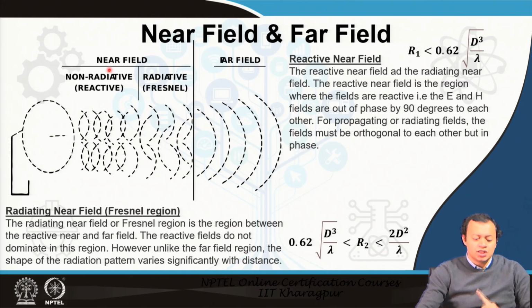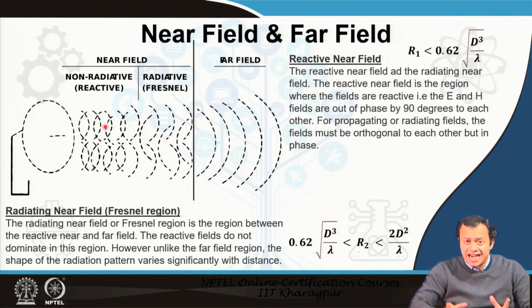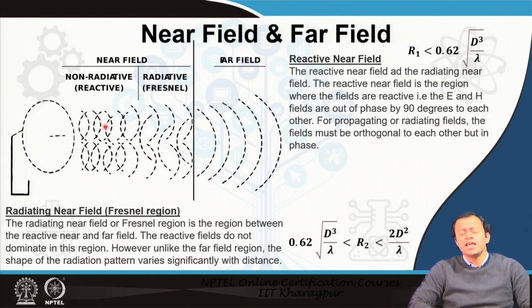The most important thing about near field is, first, it is non-radiating, that is, it is a static or standing wave. Secondly, it decays exponentially as we increase the distance. Therefore, several times it can also be considered an evanescent field, but the jury is still out. Evanescent field technically is not near field. There are similarities and overlap between them, but there are a few subtle differences. Evanescent field is the ghost, the penumbra.